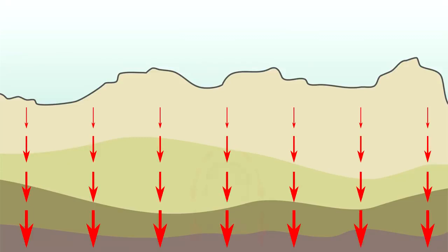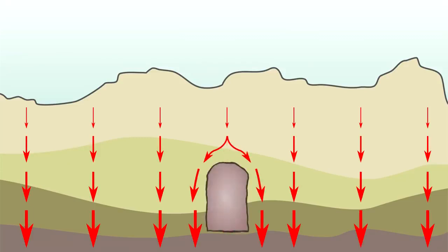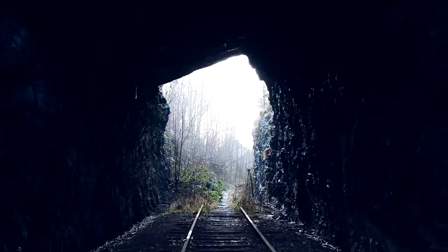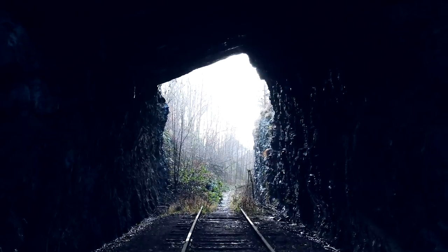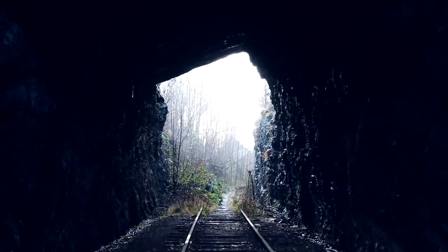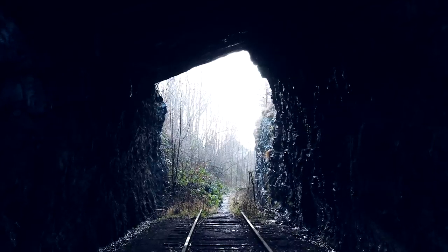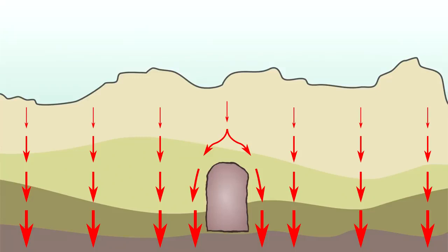Building a horizontal passageway, or a tunnel, through this material interrupts the flow of these compressive forces. Just like if you remove a column from a building, excavating a tunnel takes away the support from the material above. Where you once had compression throughout the subsurface, now you've created a zone of tensile stress, where the material above the tunnel is trying to pull away from itself.